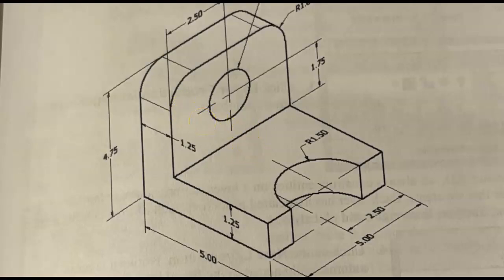Now I'm going to hit the F7 key and turn on the grid. Notice both my grid mode and my snap mode are on as well. We're going to take a look at these in a few minutes, but I don't want the orthographic grid. So this is the orthographic grid. We're going to change that right now to the ISO plane left.